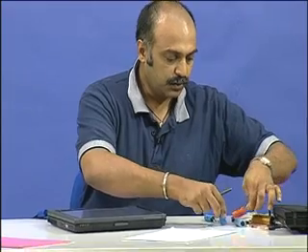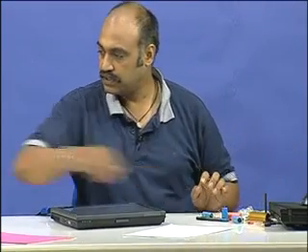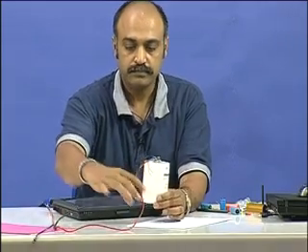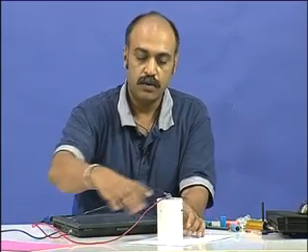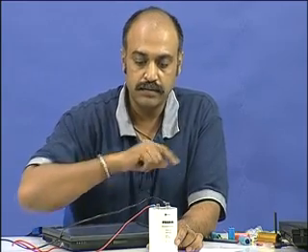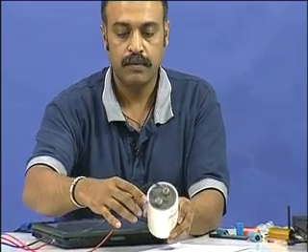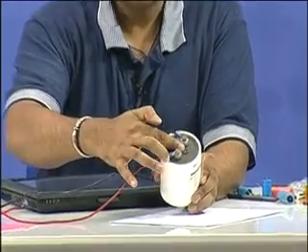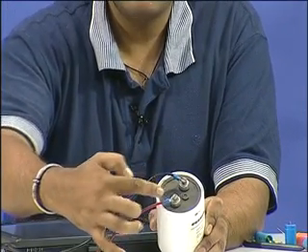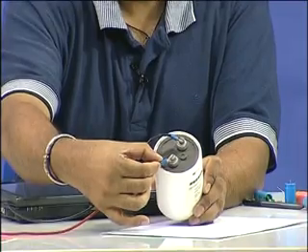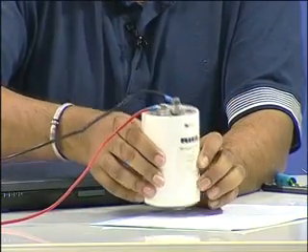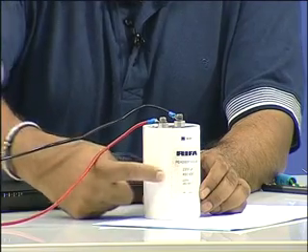I will now show you one more capacitor which is still bigger in size. Look at this capacitor. It has two terminals, okay, and this is a polarized capacitor. If you can see here, there is a plus mark, which means that this terminal has to be more positive with respect to this terminal at every given point of time. And here you will see the